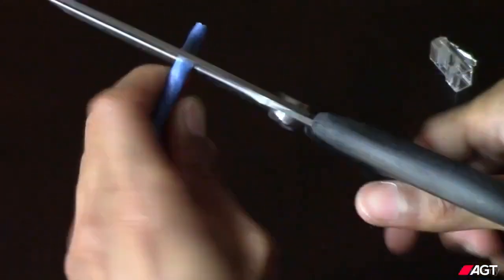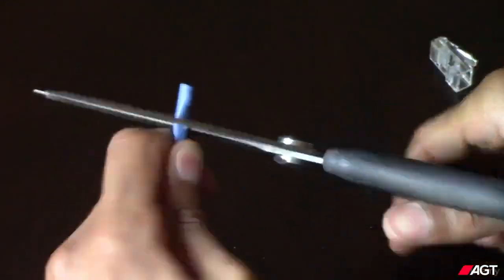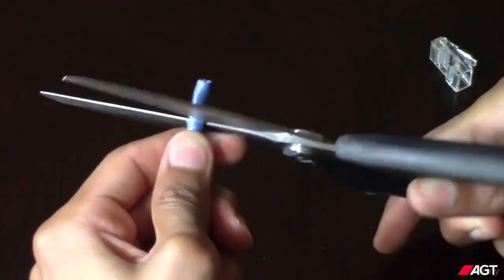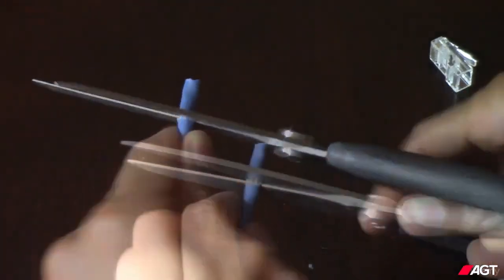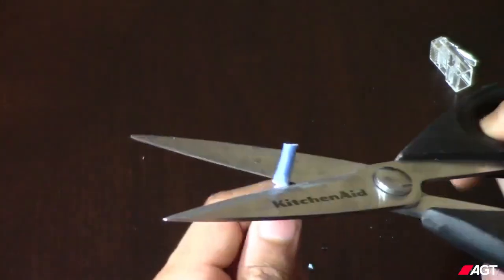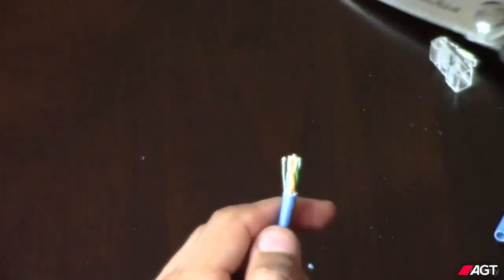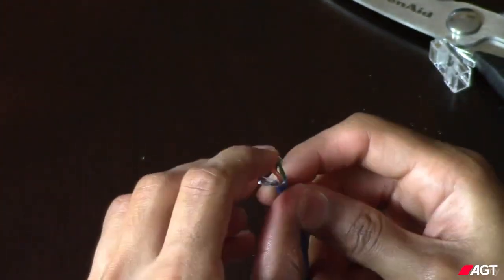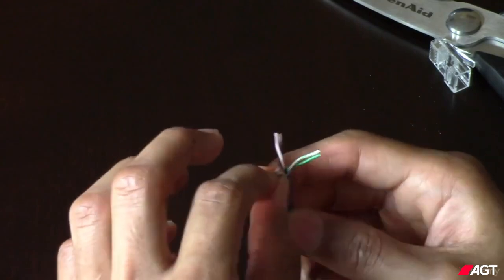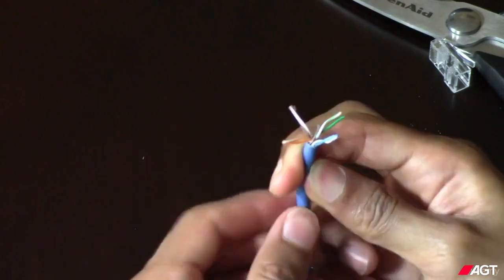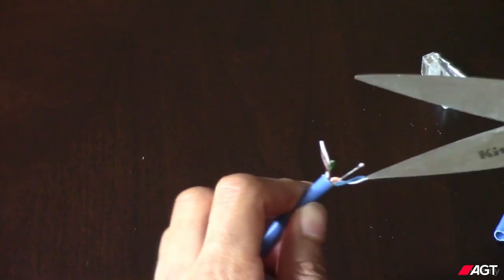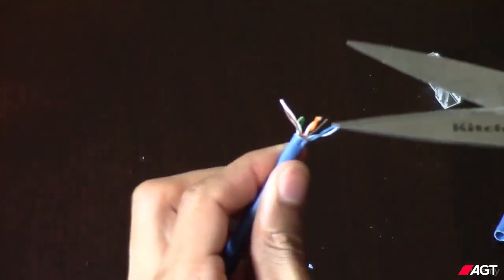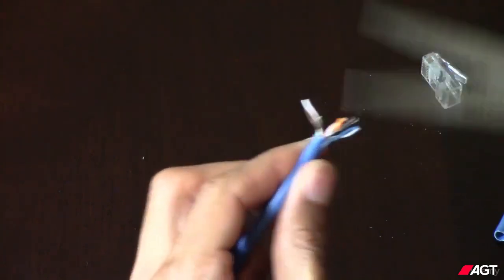This will be a lot easier if you have good sharp scissors. Like I mentioned before, these scissors are purely for demonstrational purposes. I would not use these on a job. Once you see some tears, just rip it right off. Now we have our exposed wire and nylon cord. Take your scissors and cut a small slit into the shielding. You're going to use this as a guide for your nylon ripcord.